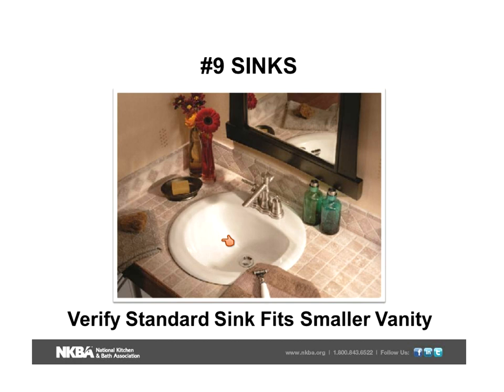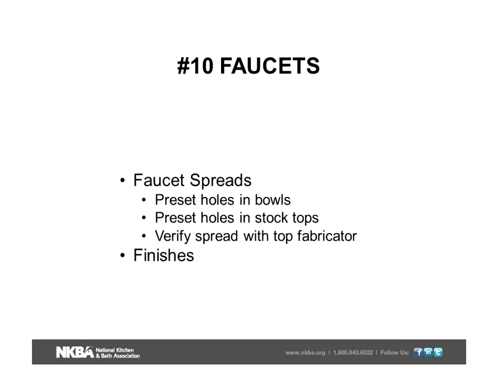Also, we want to be sure that for any of the bowls the client has chosen, because of door clearance, you're going to have to use a little bit smaller vanity. Will that bigger bowl fit in that smaller vanity size? And I'm talking about 1 to 2 inches will throw you off, so be careful with that. As far as faucets are concerned, the faucet spread varies.